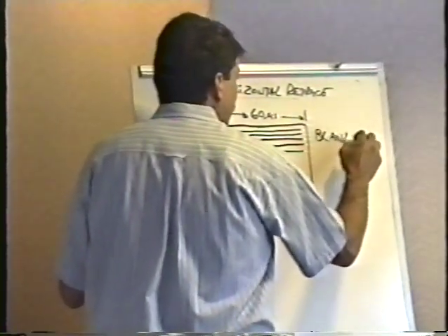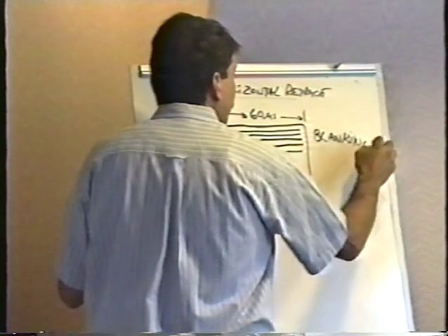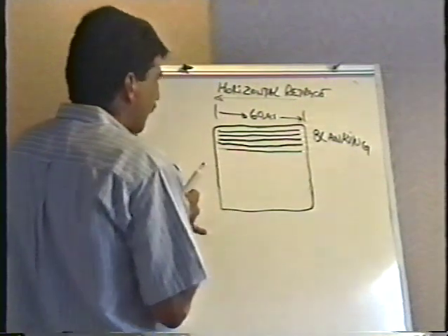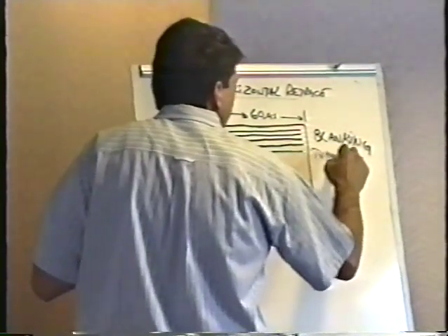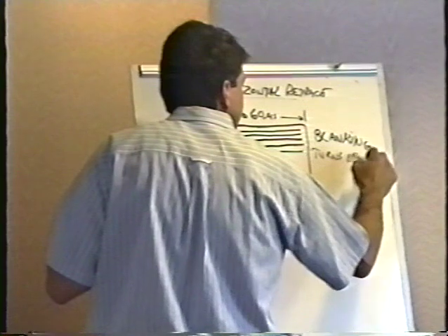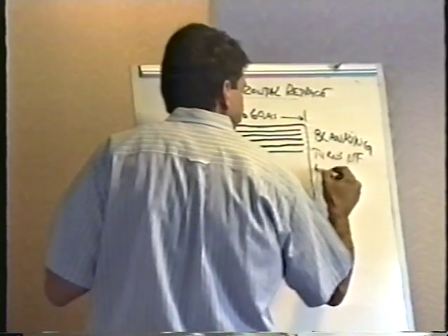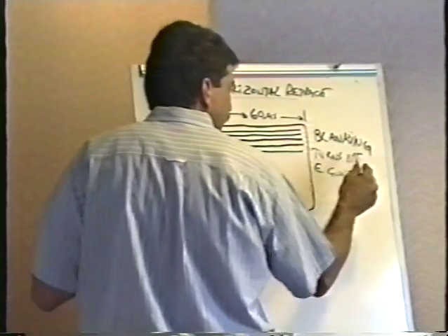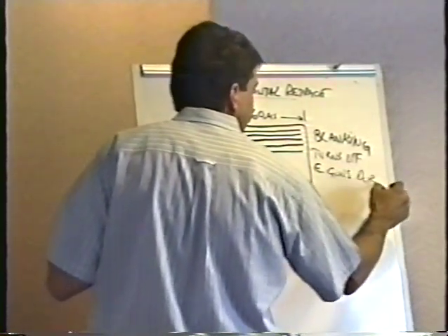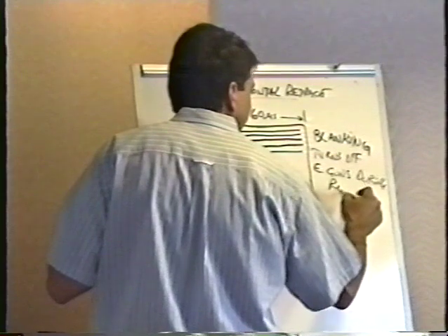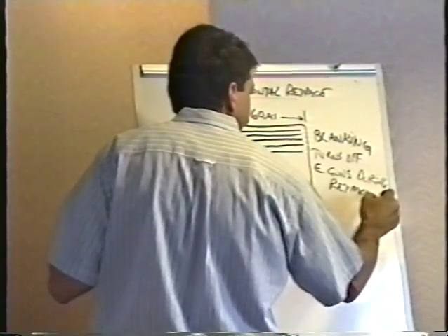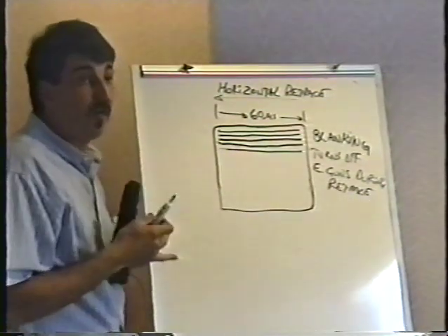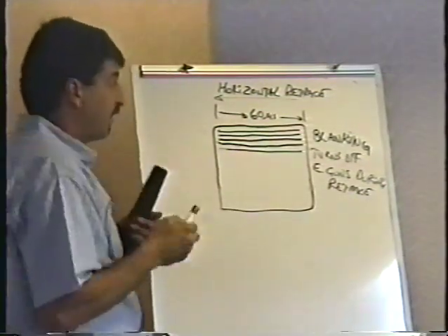There's a circuit in the monitor called the blanking circuit. The blanking circuit turns off the electron guns during retrace. When the beam is at the right and it moves back to the left, we don't want to draw a line, so the blanking circuit activates.